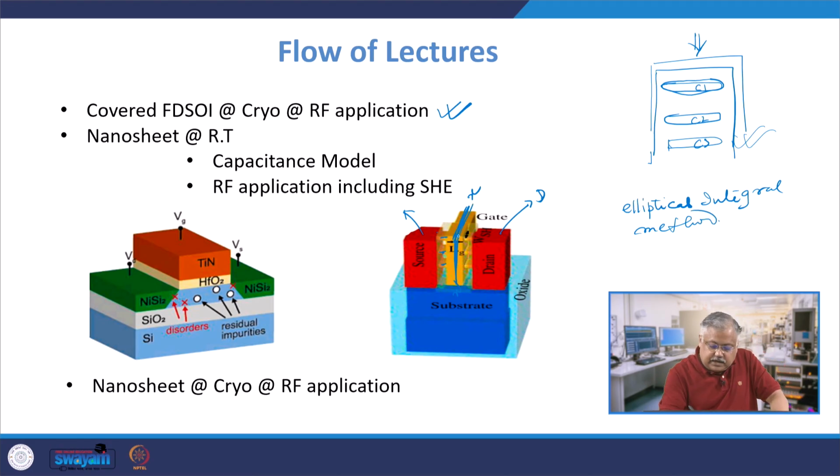So this is the gate, and I have a source here. This is the underlap region which you see, this one. You don't have the gate overriding it. So basically, the channel potential here is relatively larger as compared to one within the gate itself.